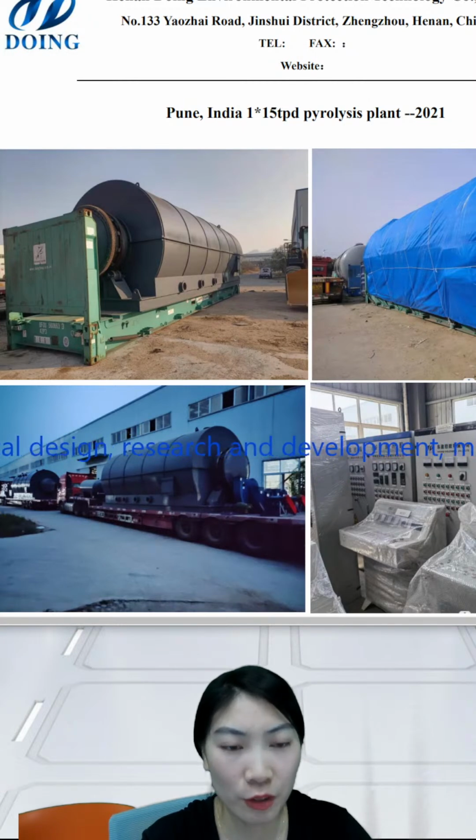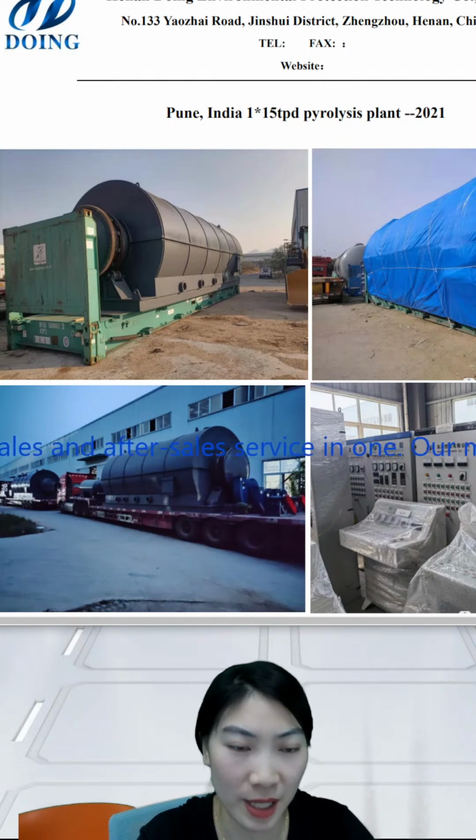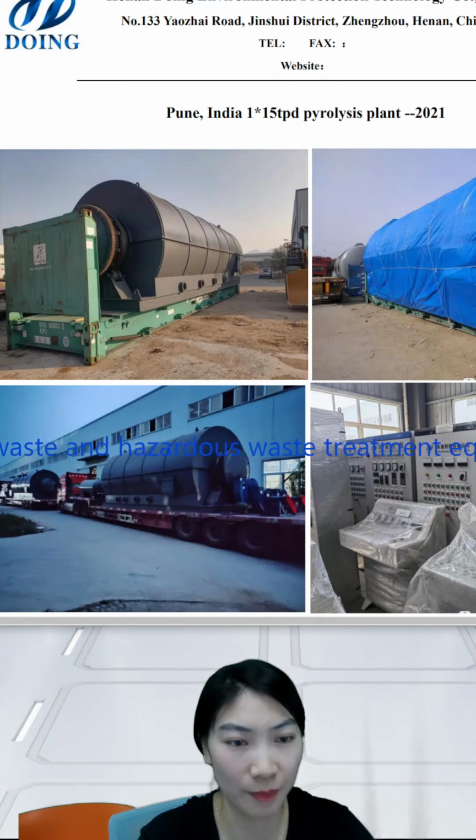For the fully continuous pyrolysis plant, normally we suggest you use rubber powder, normally about 5 mm rubber powder, as raw material to feed in. Because our fully continuous pyrolysis plant can run for 2 months without stopping, 24 hours every day, so we need to ensure there is no material to block the system.